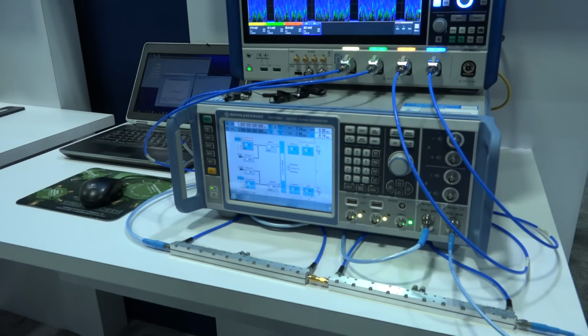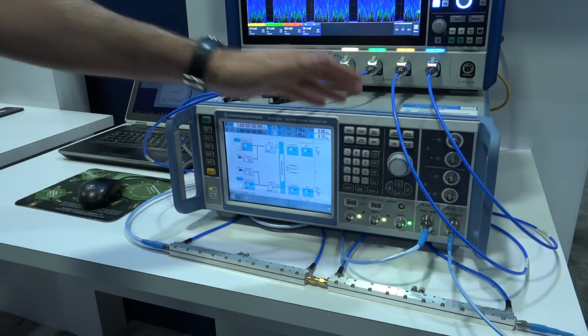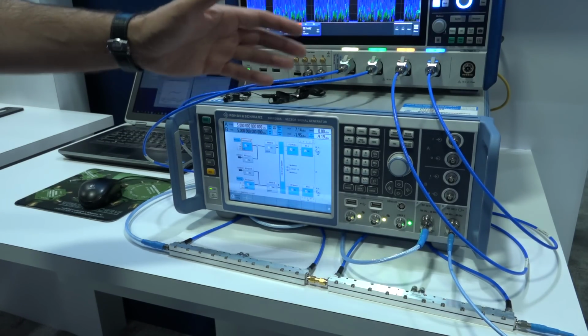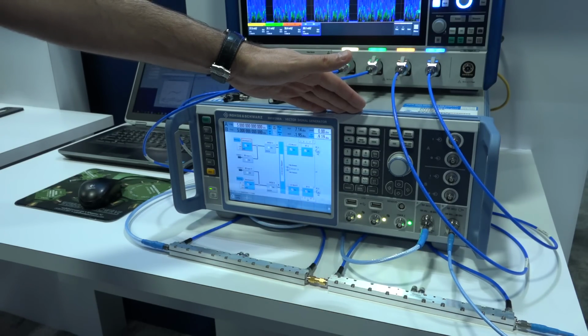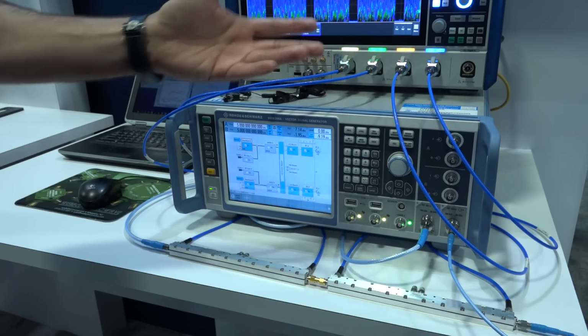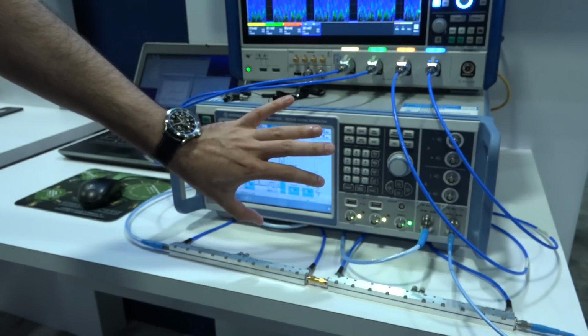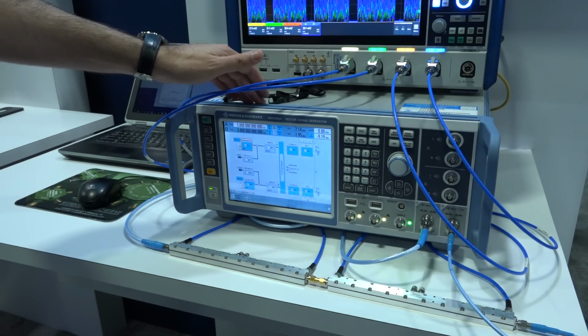One other item to note is that you do have 2 gigahertz of bandwidth and 2 gigabits of memory depth involved here, so you can actually do your modulation quite broad. And because of the depth, any particular memory effects that could be inside the device you're trying to do a load pull on will also be captured. But those are basically the capabilities of the generator. We're just leveraging them for the load pull capability.